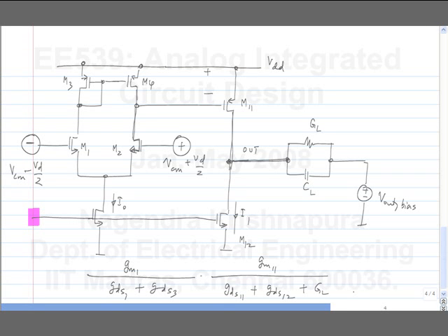So fine, the DC gain is certainly higher, and also it's not very sensitive to GL. If we drove GL with, let's say, a folded cascode amplifier, then the gain is approximately inversely proportional to GL. Here also it is, but the first stage gives you a high gain. You can design the first stage to give you whatever gain, and the gain of the first stage is not affected by GL. So you don't have to make any of the GMs 100 times the load conductance to get a gain of 100.